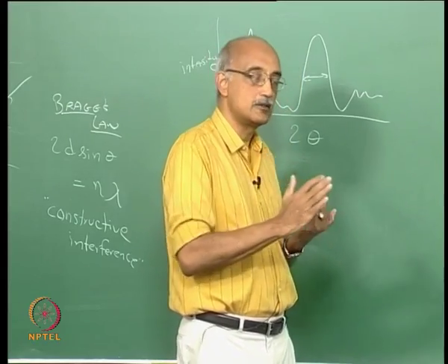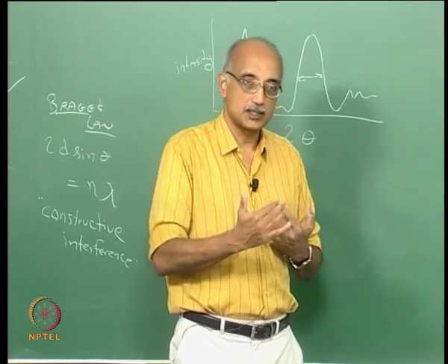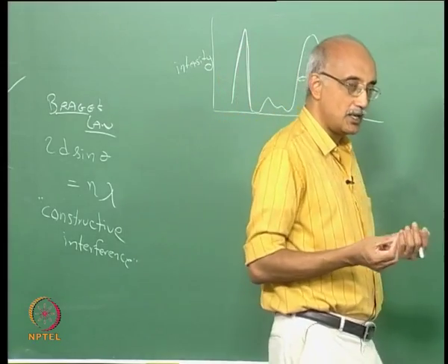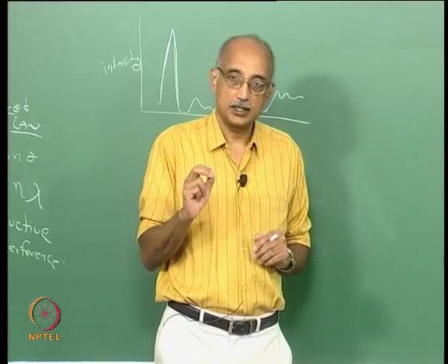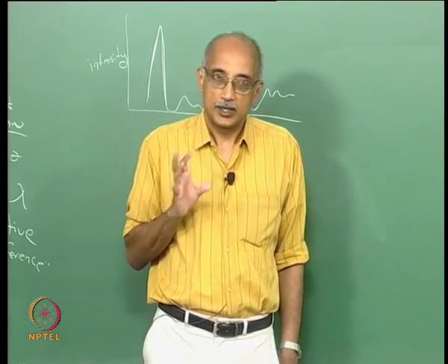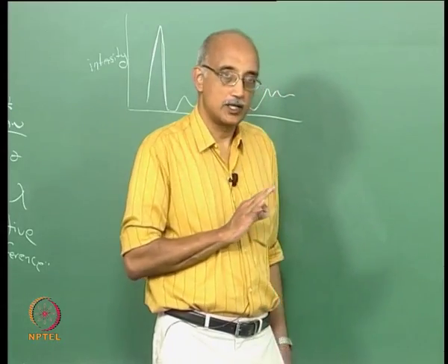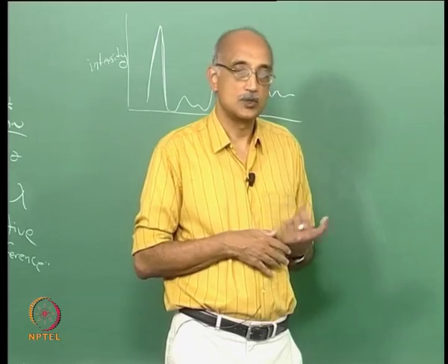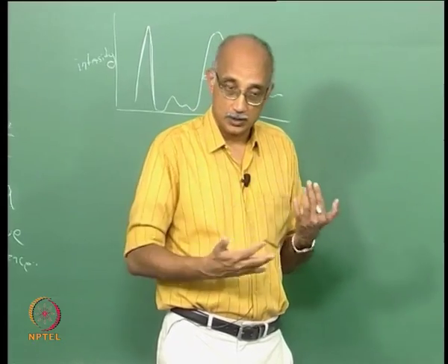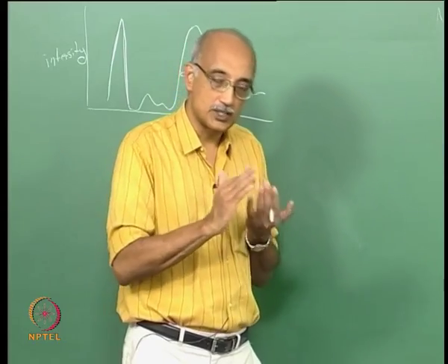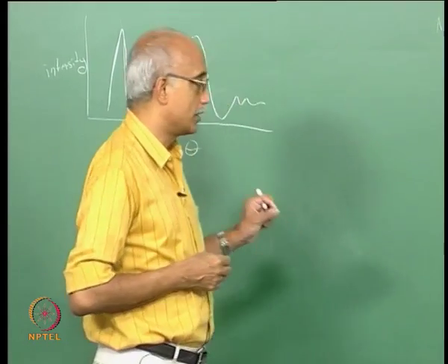as a line monitor. For example, let's say you are manufacturing or synthesizing a crystalline material and you want to make sure that the process is under control, then an SEM-TEM is not the right tool to use. XRD maybe, XRD is probably a good tool to use if you are primarily concerned about the crystallinity of the material, but if you really want to know whether the process is under control, the simplest technique to use that will give you a variety of information is AFM, because it gives you not only the structure of the material, but it also tells you something about the morphology of the material, the three-dimensional topology, tells you something about the roughness of the surface. So it's a very powerful tool that can give many types of data that are useful for a particular process,